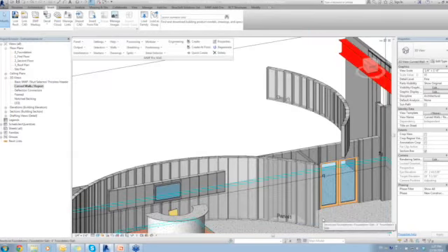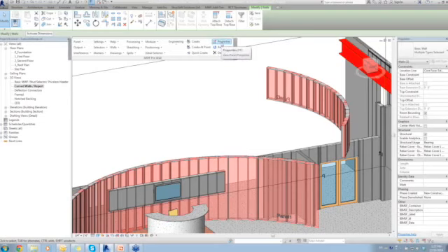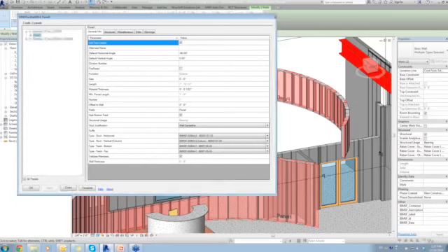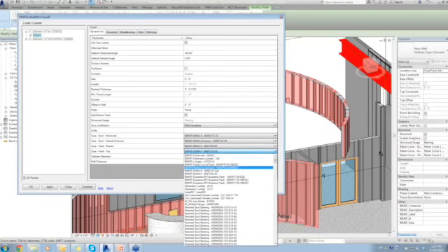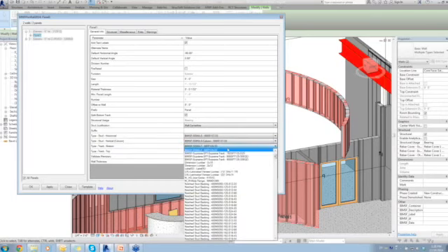Those have been loaded into my project, and simply by selecting these two panels, both containing these two walls, I'm interested in selecting both of these panels. I can see that they're framing the top and bottom track just with these generic SSMA members. So I can change it to, this is my top track, the 125, and my bottom track to the,